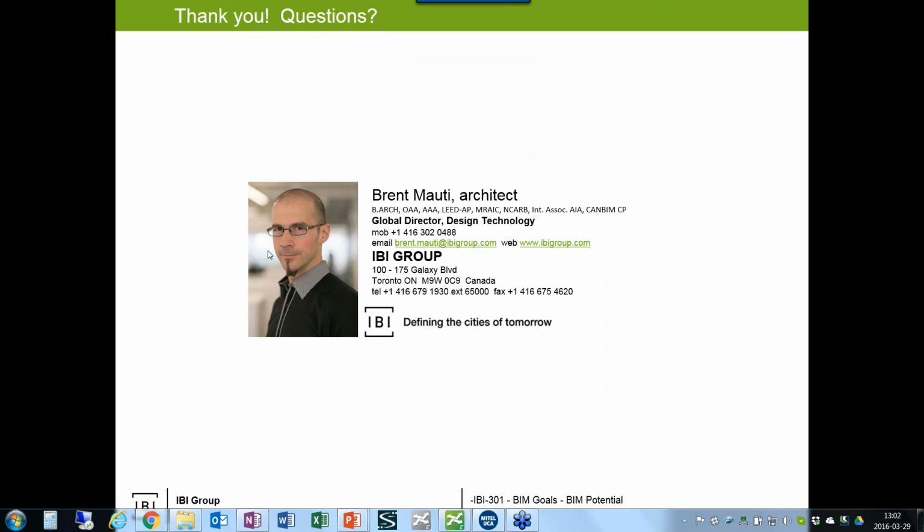Is there an app to use the BIM model on the iPad for site use? Yes, yes, yes. So it's fun. There's a couple different approaches. Number one, we have to identify how you're BIMing. Are you in Revit, in Civil 3D, in a Bentley application, et cetera? So there's all the BIM authoring tools. Then we can take an approach to get it to something like BIM 360 Glue, which is an Autodesk application that can be used on an iPad.